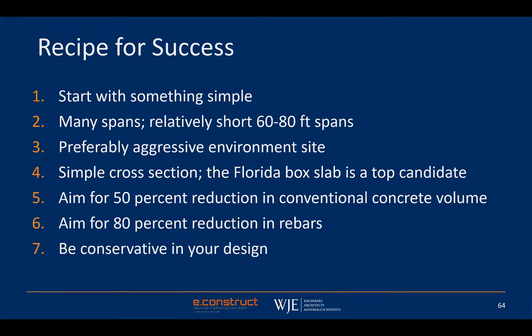So, in my opinion, the recipe for success: start with something simple. Get as many spans as you can on your project to try to get into the steady state and optimization process. Start with relatively short 60 to 80 foot spans.